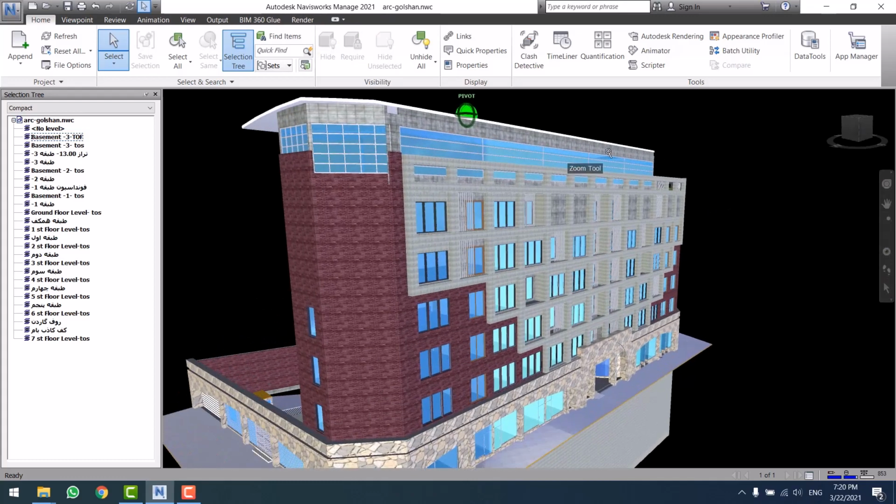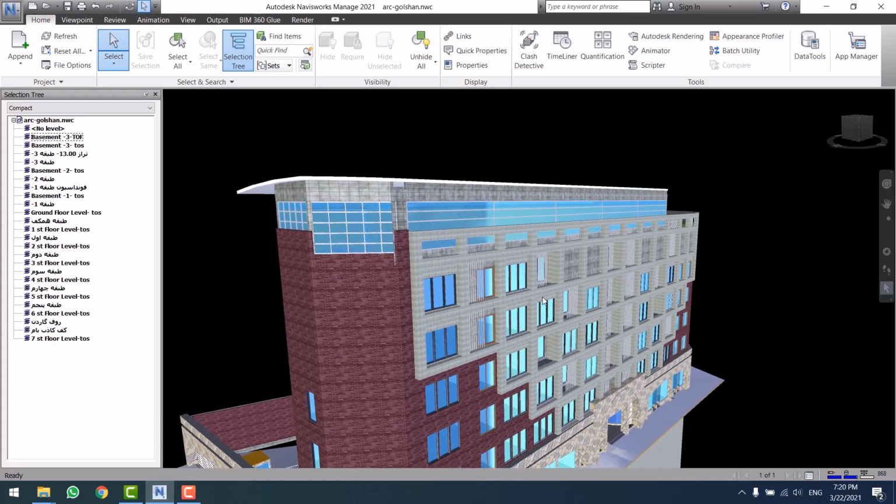Normally in Navisworks dragging is not available, as you can see, and you are just able to select a single object. Check this out, I can select only single objects, not dragging. But to be able to draw a box, I open the Select menu and I enable select box. After that, we will be able to drag. Check this out. Right now, as you can see, keeping the selecting box unavailable is nonsense, since clicking and dragging is available in all software.